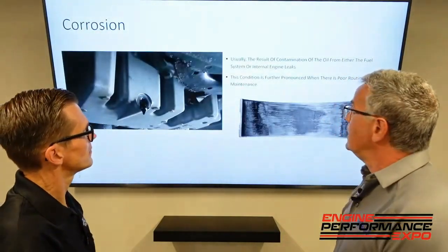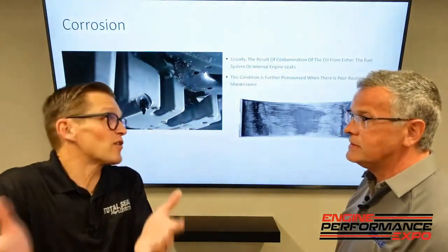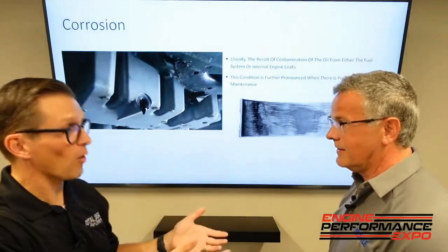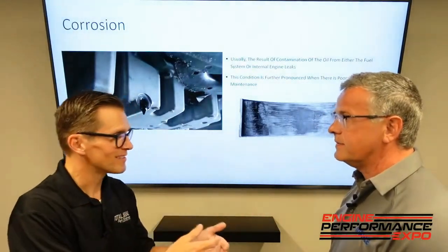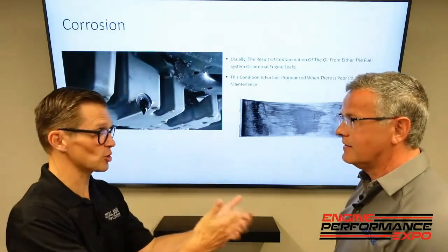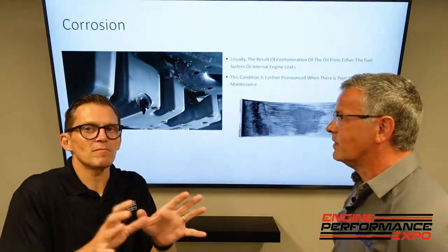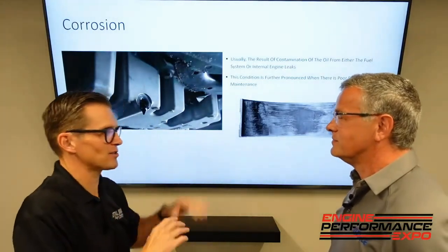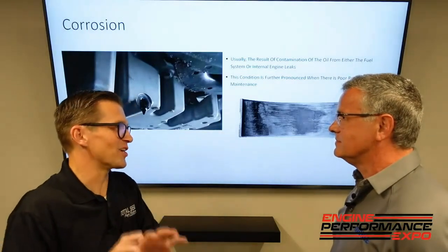Well, it says right here, fuel, right? Fuel is the enemy of your oil. I talked about it before. The same base oil that's used to make engine oil is also used to make turbine engine oil. And an oil that may last, say, 3,000, even 5,000 miles in a passenger car can literally last 30 years in a turbine.